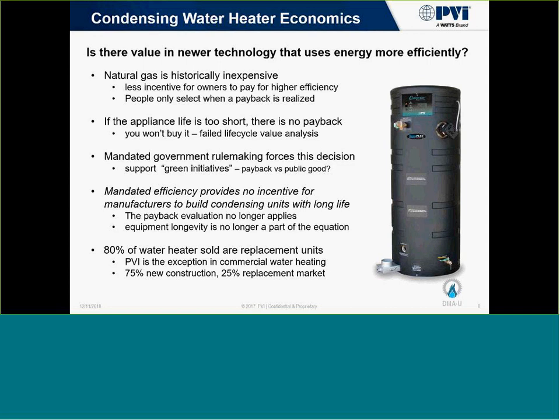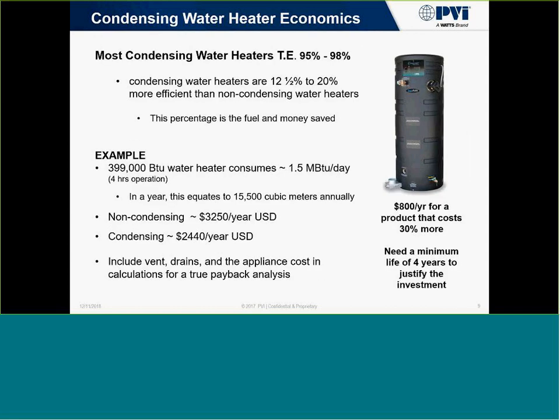But if the life expectancy of that condensing water heater is short, you're really not going to utilize the payback for the added cost that goes into manufacturing that high efficient unit, because of the other installation requirements that go into installing the high efficient, and then also just the materials that it requires to manufacture it.